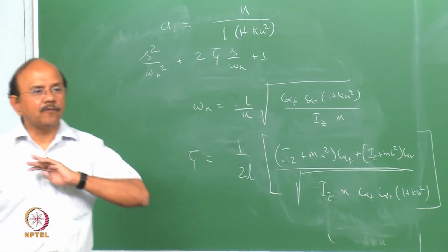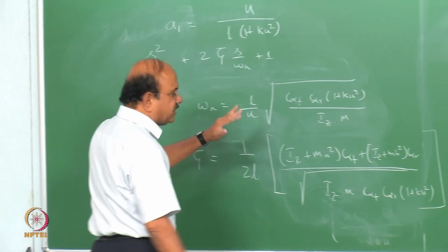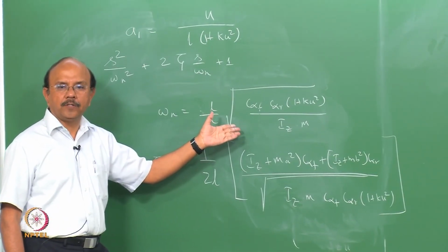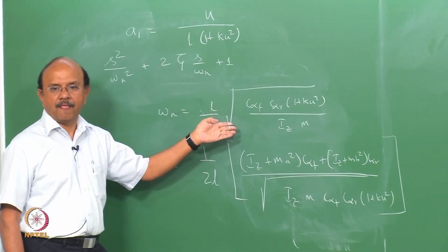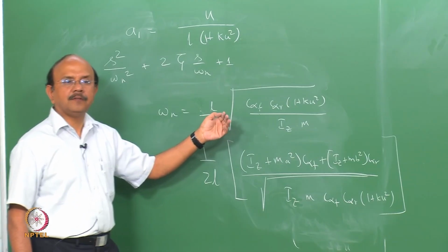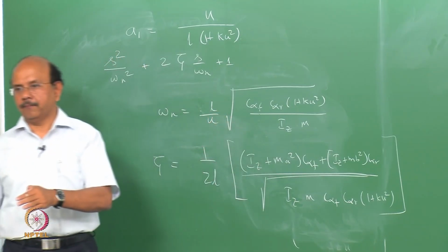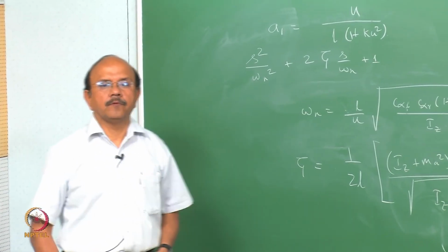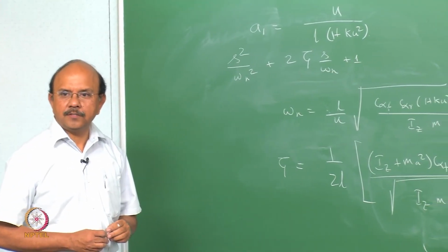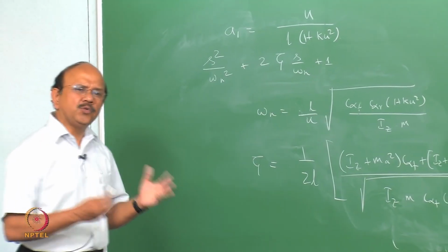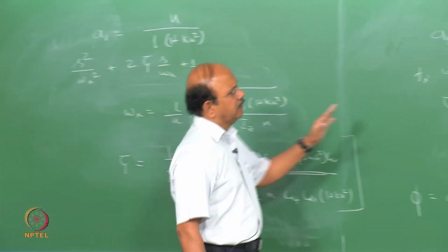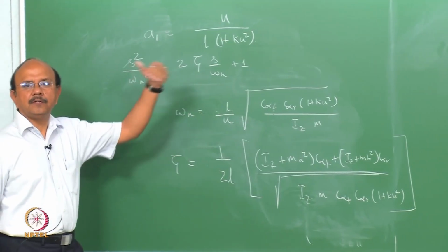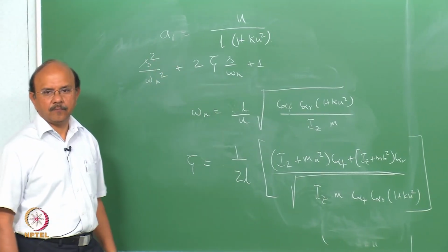In fact, if you remember, we have linearized the tire characteristics and just put that initial slope. Not bad, not the best way, because we need other tire models. But we usually assume that we are not going to be away from the linear case.